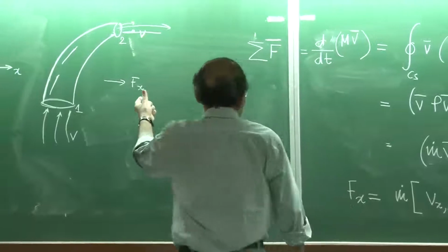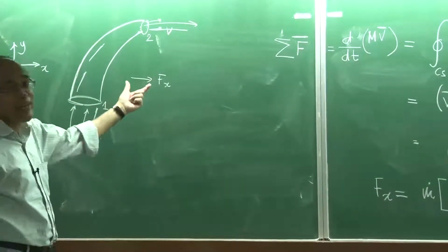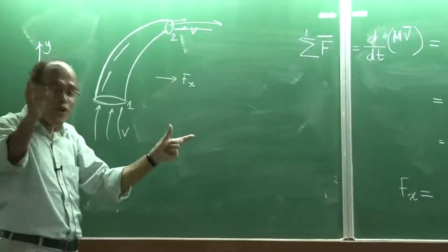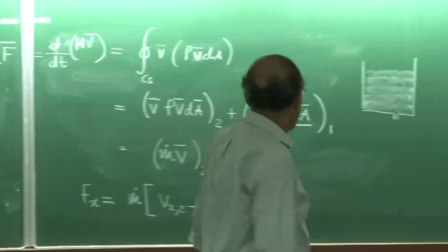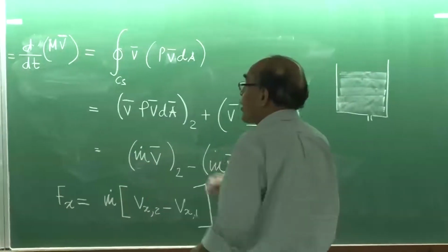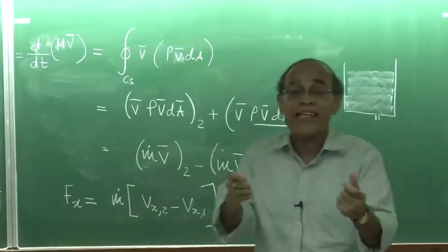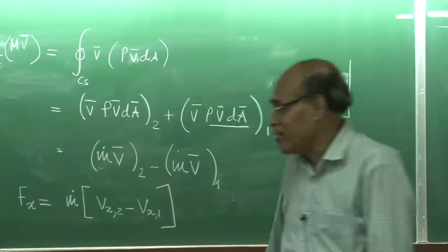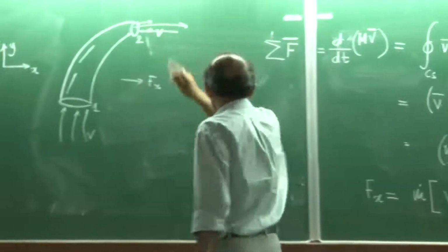It is the same momentum conservation principle at steady state that can be applied to find out, for a given configuration and geometry of such firefighting hoses and guns, what forces are being experienced, because if too large a force is experienced, the person may actually be dragged by the flow which is flowing out through the exit nozzle.